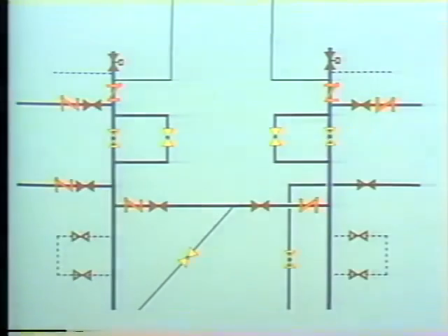On this symbol, the slanted line indicates the disc inside the valve, so the symbol itself indicates that flow is from left to right. On our print, you can see that the check valve symbols can help us determine how a system operates by showing which way the fluid flows.